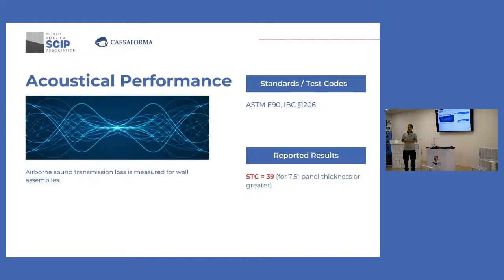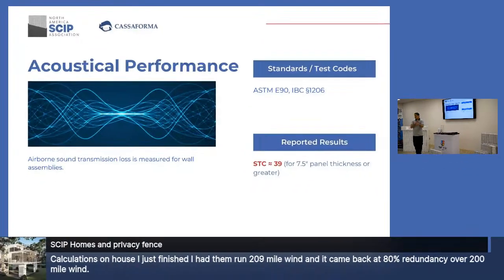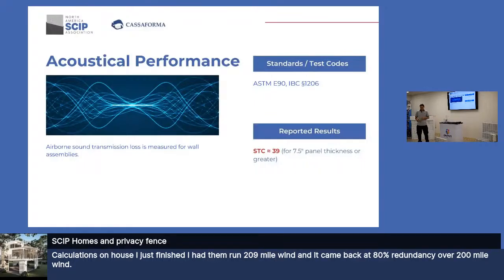But about the sound insulation, that is a little bit tricky because sounds are not equal. It depends on the frequency. Usually high frequencies can be handled better with the foam. So if you are in the exterior, the high frequency works well. If you are speaking about a hotel and you are concerned that from one room to the other people don't hear a knock or something, that's low frequency. So low frequency requires more mortar. And there are some places where you can create some choices to improve that situation.